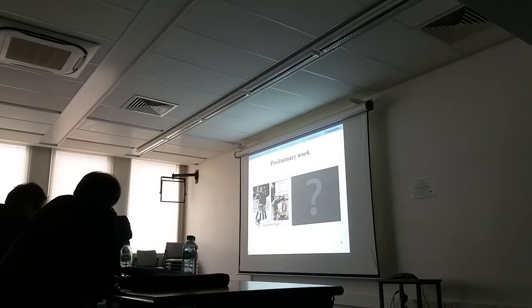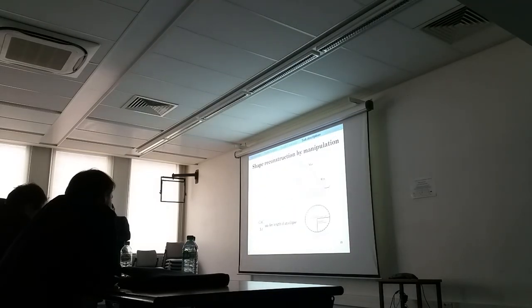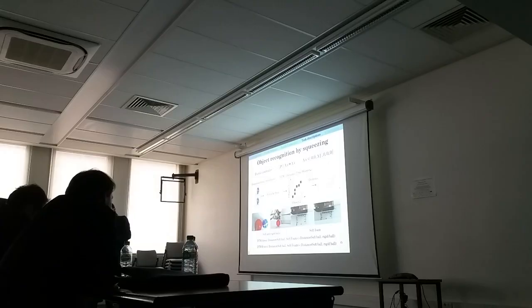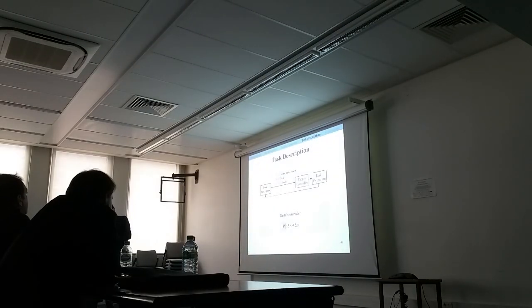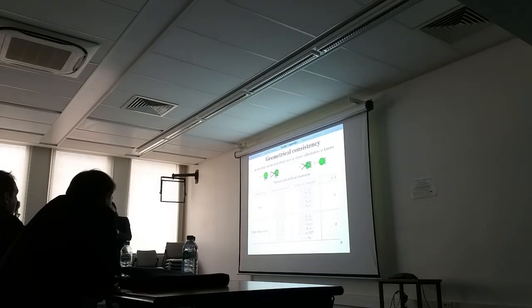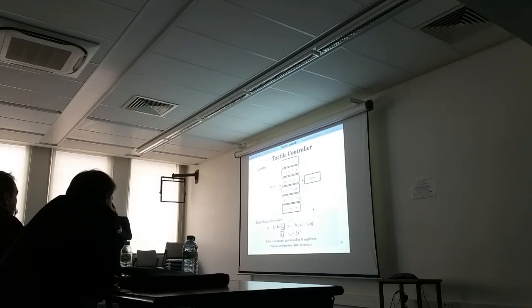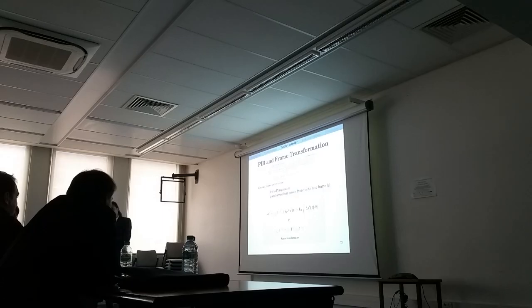When you look at the curves, there is a difference between the ATI sensor acquisition and the tactile sensor acquisition. There is still a big difference. Yes, there is, and it's only because the real measurements that are provided by the ground truth force-torque sensor, we somehow tune the piezoresistive sensor to have the same values. However, they always change due to some creep behavior and temperature variations. So it's only a proxy of the real forces.